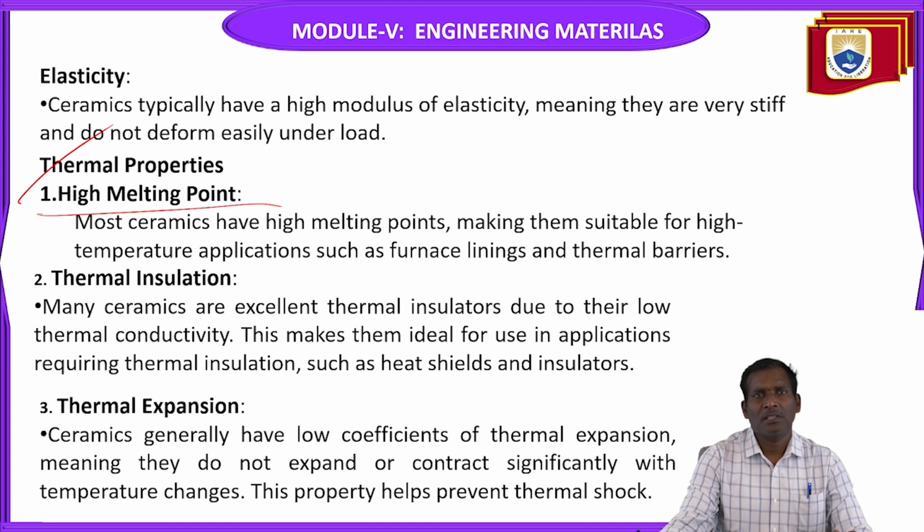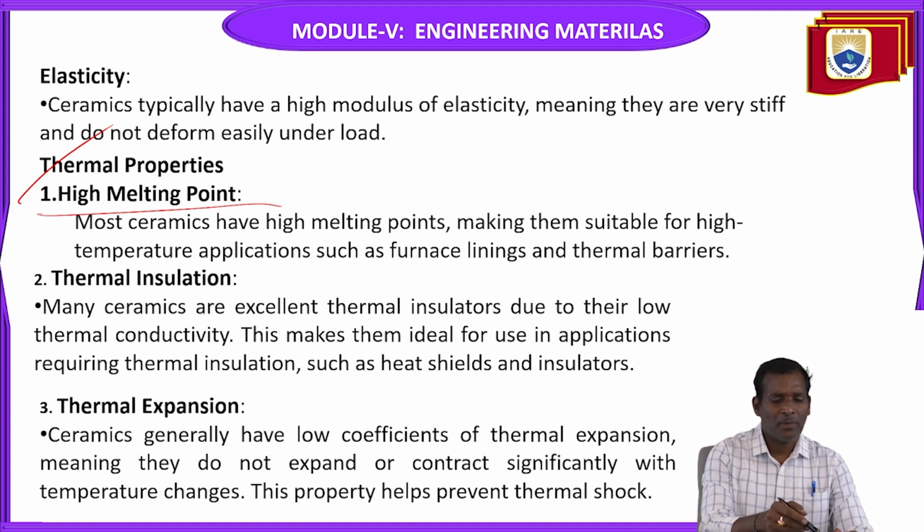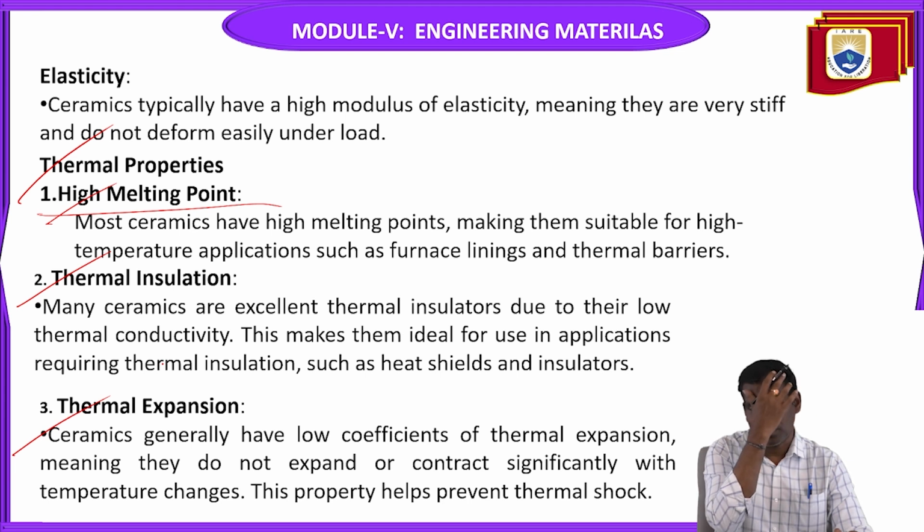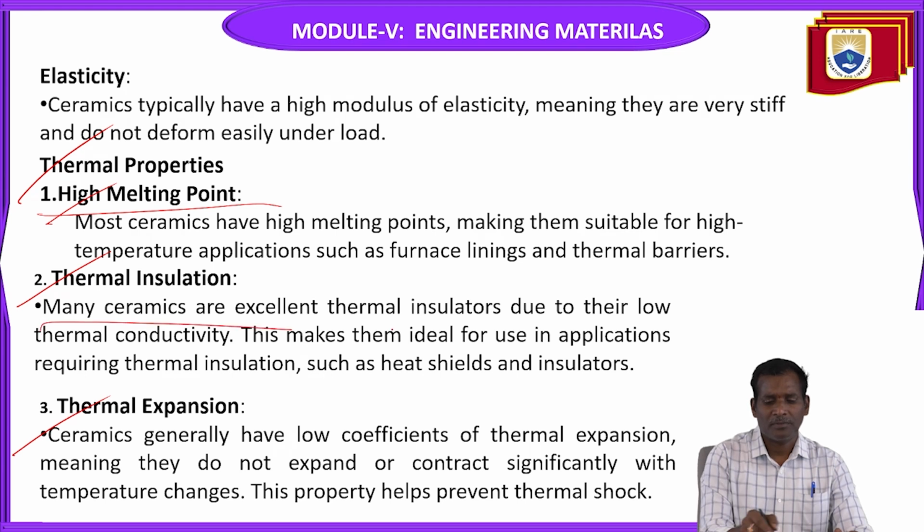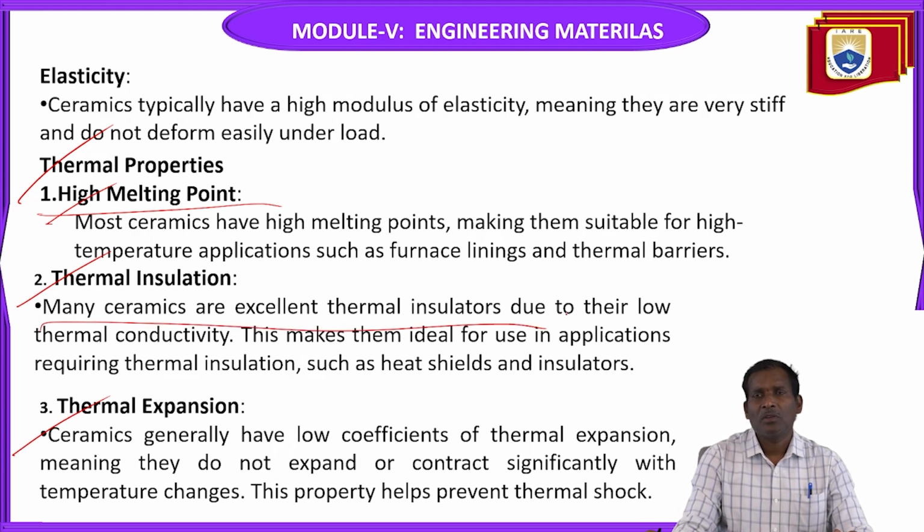The thermal insulation, high melting point and thermal insulation and thermal expansion, all these are related to these thermal properties. Thermal insulation, many ceramics are excellent thermal insulators. Why? Because due to their low thermal conductivity property. So this makes them ideal for use in applications requiring thermal insulation, such as heat shields and insulators.